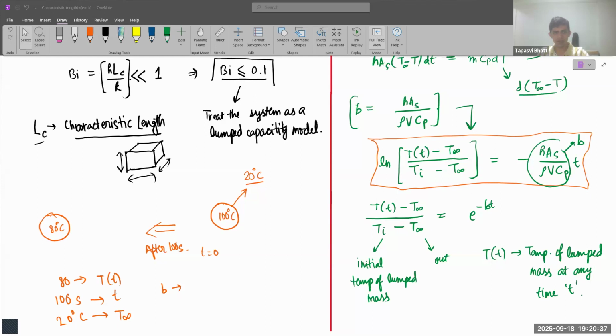After that, we have diameter, which is generally less than 1 mm. So you'll have to go through the slides once, and only then will it make sense; without going through the slides, it's going to be difficult to explain this. But as of now, just in case the question mentions the gauge number of the thermocouple, we can know the diameter of the thermocouple wire using this table on slide 16.